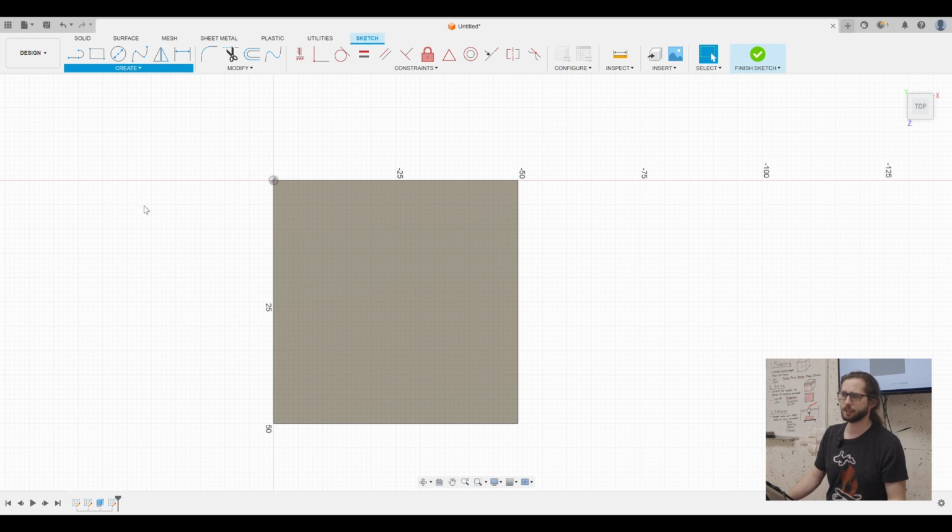You can see down here, Project, Include, Project. And what that does is it's basically like shining a light on your object, and where it hits this new sketch that we've created, it will give us an outline of where that exists, right? And the hotkey for it is P. So you can always just hit P. And so now Fusion's going to say, all right, what is the thing that we want to project?